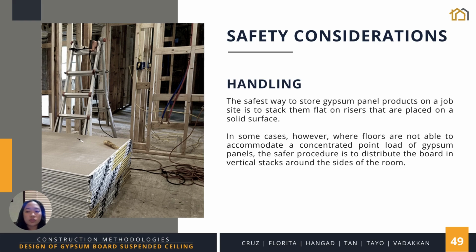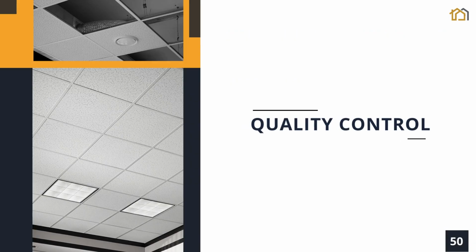The safest way to store gypsum panel products is to stack them flat on risers that are placed on a solid surface. They shall not be stored in a single pile, but rather spread out evenly to distribute the load. In some cases, however, where floors are not able to accommodate a concentrated point load of gypsum panels, the safer procedure is to distribute the boards in vertical stacks around the sides of the room.